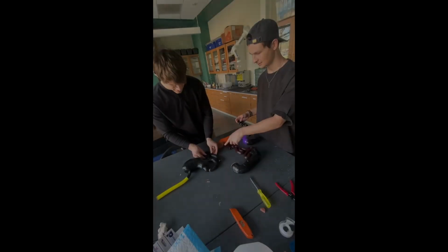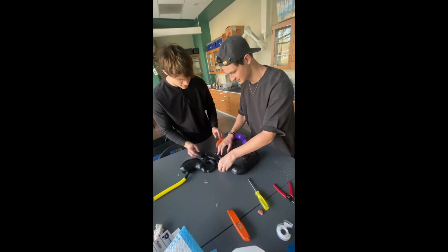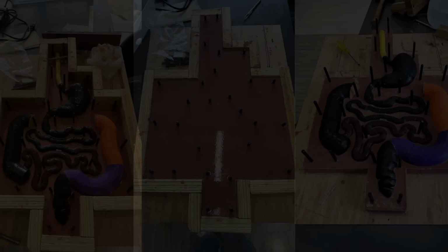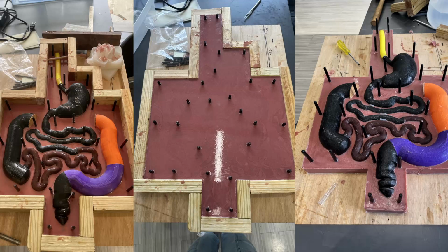We designed the model in SolidWorks, printed it in 8 sections, and glued them together. Then, we repeated the silicone pouring process, this time using 6 gallons of silicone dyed to simulate the natural color of the intestines. We also built a custom containment frame from 2x4s to help reduce silicone waste and match the model's unique geometry. Dowel rods were inserted to help align and secure the 2 halves.